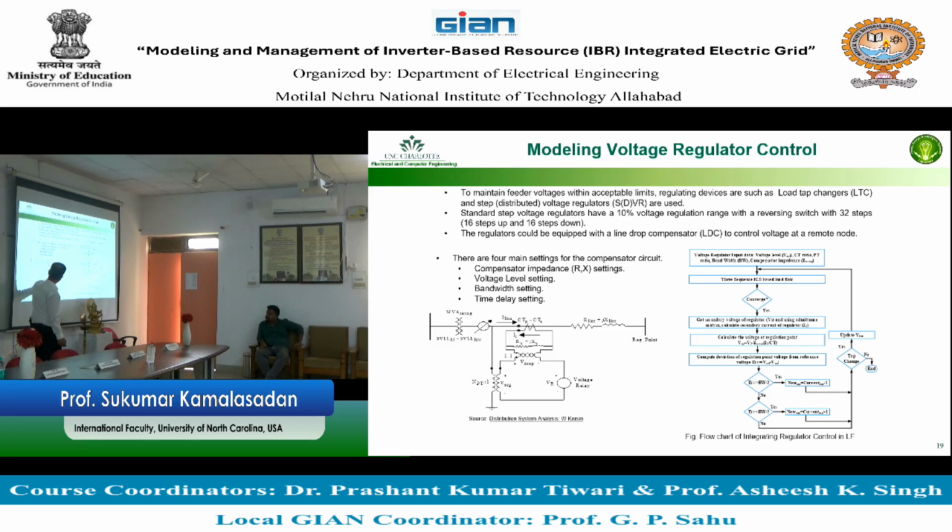So it's tracking the power through PTs and CTs, and that power is going to go through a voltage relay loop, and it is trying to look at the voltage, and that voltage is used to change the tap. This is the operation of the load tap changer. Okay, so we talked about the load tap changer. What is a load tap changer? How does it work? It looks at the load and then taps the transformer voltage. Okay, so now you have a question. I think we discussed this.